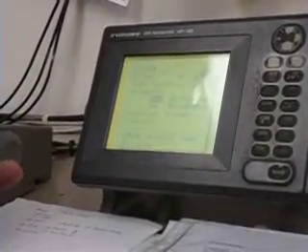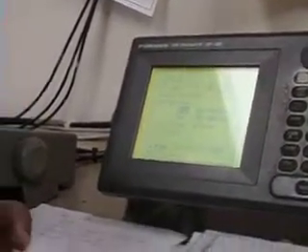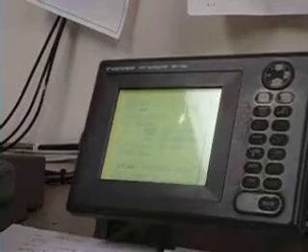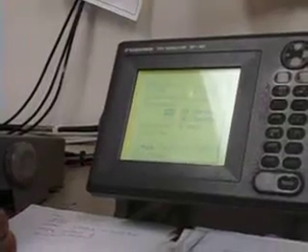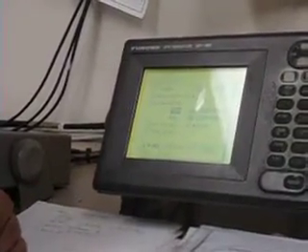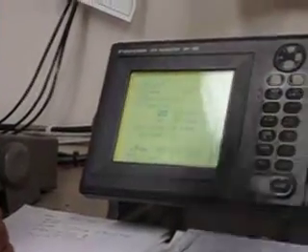Now if you put too much smoothing, not 000, say 100, and this one is 200, what will happen? Now if you alter course 30 degrees starboard, it will not show that you altered course. So again there is a little bit of fine tuning there. Not too much is good, not very little also good. So if you alter course 10 degrees starboard, the machine within a few seconds should show you that you altered course 10 degrees to starboard.